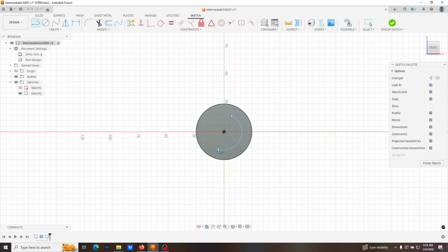Now, one of the things which I'd love to talk about, which, not that I love it, I will talk about, is how differing constraints can work around and things like that. But on this one, I don't have particularly any sort of constraint set between the center and this line here. But because this arc is defined as having that center point, I don't need to do it. So the rules can kind of add together. But oh, I actually no, I lied. I still need to put it there because it'll shift out there. So I told on myself.